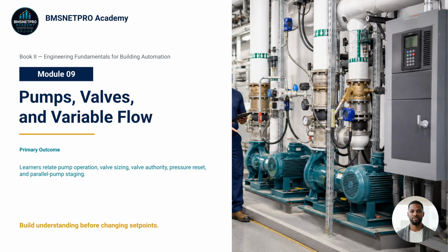As BAS professionals, we need to understand pump curves, valve authority, differential pressure reset, and variable flow behavior so we can diagnose problems instead of simply increasing set points. By the end of this module, you should be able to look at a hydronic trend and ask better questions before making changes.